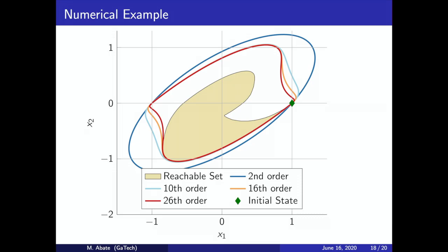Thus, even when a quadratic Lyapunov function is known which certifies the system stability, it is helpful for a system designer to compute higher-order homogeneous polynomial Lyapunov functions in order to attain better estimates of reachable sets in infinite time system behavior. In our work, this example is presented in conjunction with an algorithm for generating high-order homogeneous polynomial Lyapunov functions using the meta-Lyapunov technique presented here. We also provide a comparison between our approach and a similar approach directed by sum-of-squares-based techniques. While we are unable to provide a full analysis here as to the differences of our approach, we refer the interested reader to our publication.